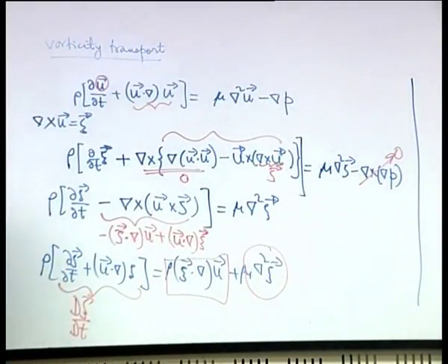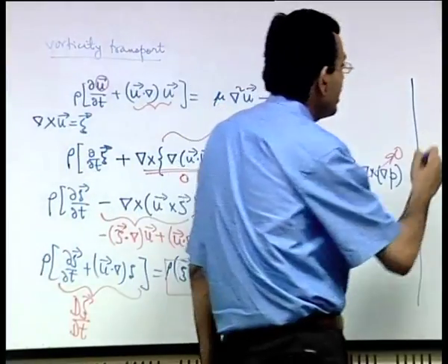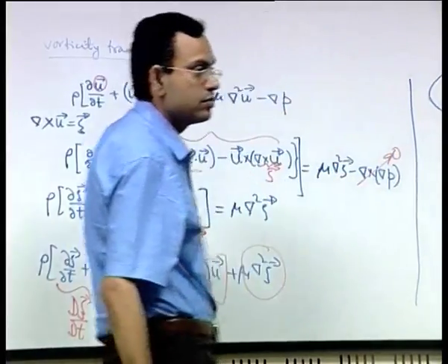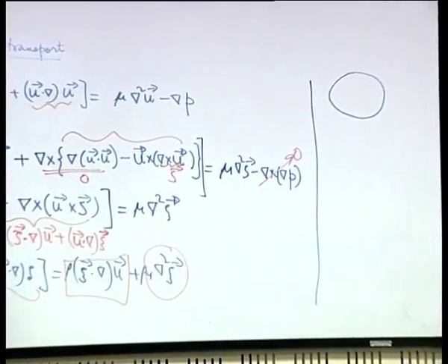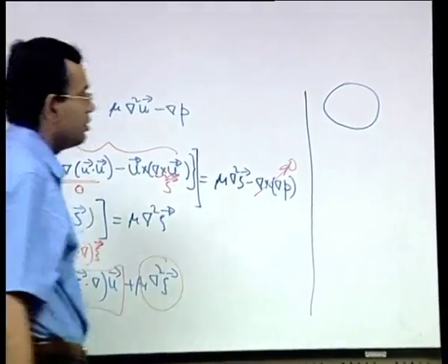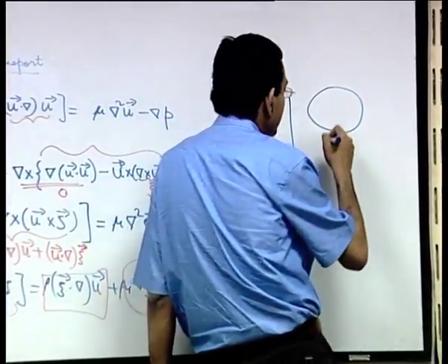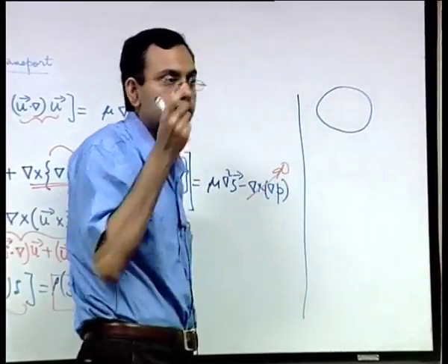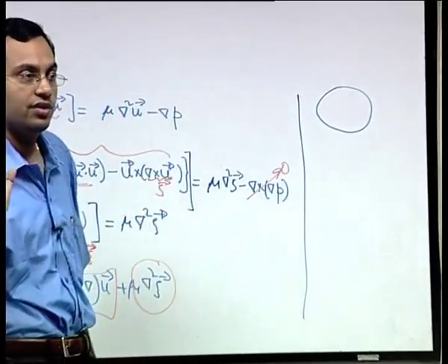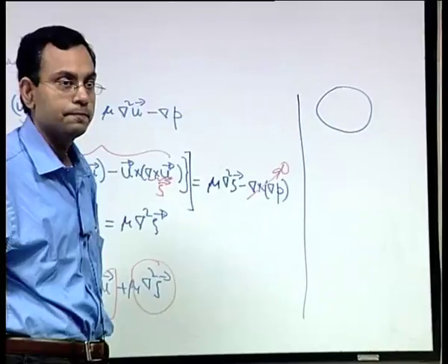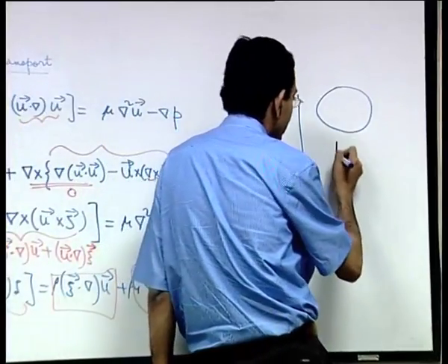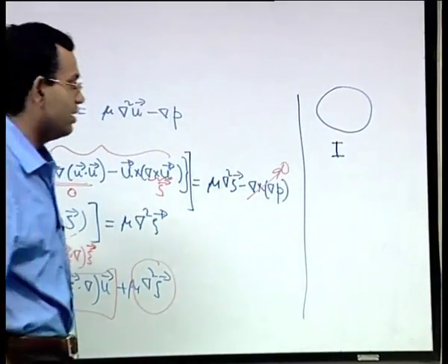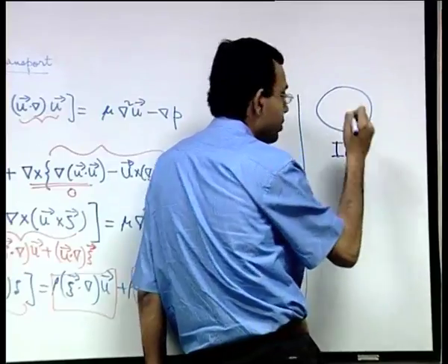Now, let us say that you have a large eddy in a turbulent flow. Now the eddy is a lump of fluid with certain rotationality, it is a rotating lump of fluid, so to say in very simple language. So it will have its moment of inertia I and an angular velocity omega.